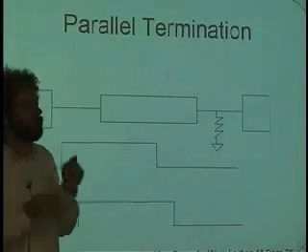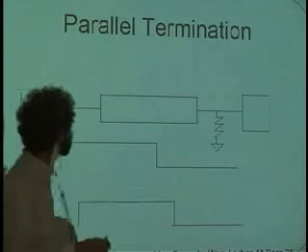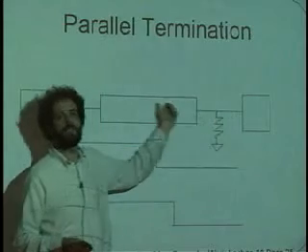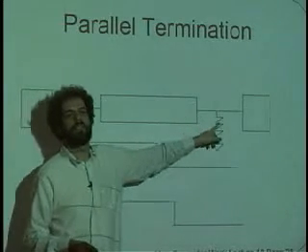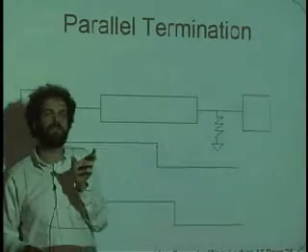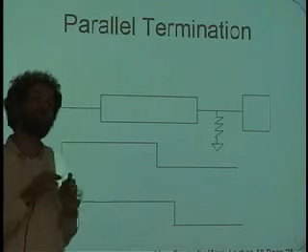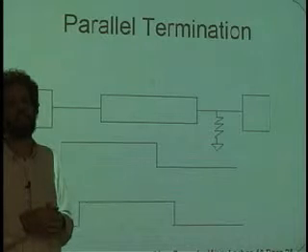And the reason is that when the computer sends a signal out on the bus towards the receiver, if it doesn't want the echo to come back to it, it needs to dissipate the energy. And so believe it or not, the terminators that you put there at the end, when data is being sent, they heat up just a little bit with the data that's being sent towards the other end of the line.